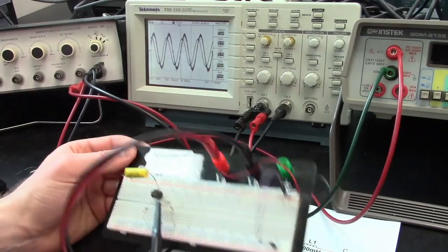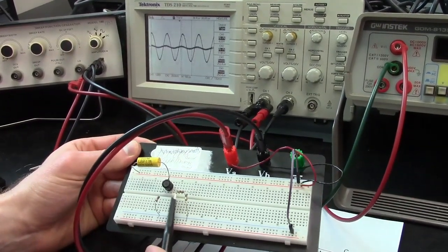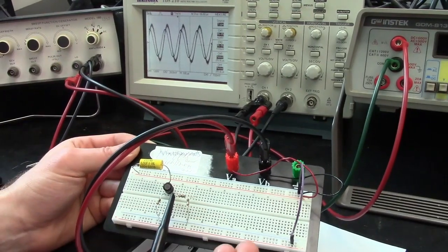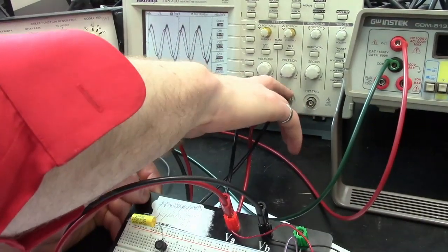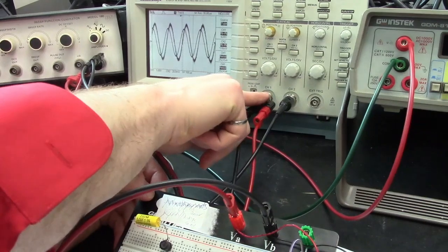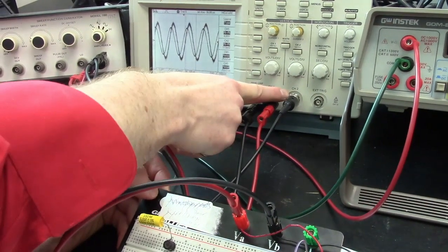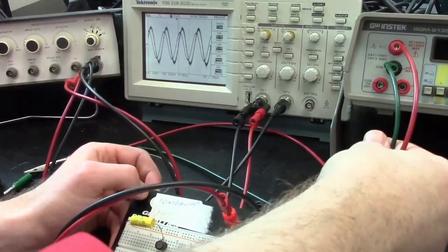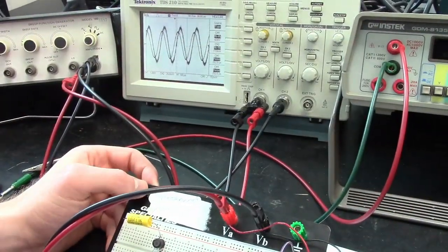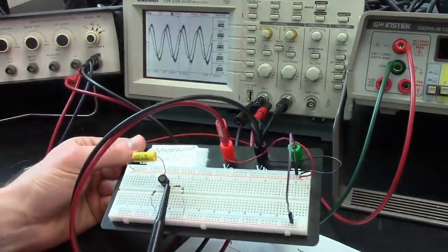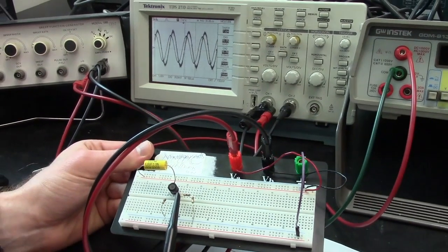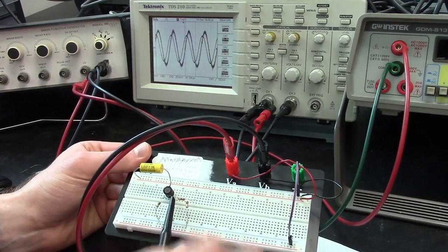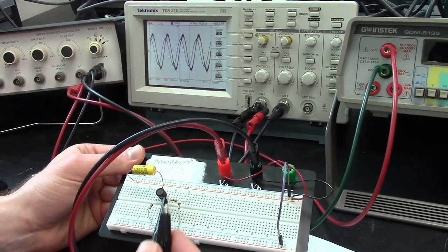So the reason we can measure anything at all when we've only connected one terminal, like what voltage is it measuring relative to, is because the scope is actually connected inside. So the ground of channel 1 is connected to the ground of channel 2. You could turn off the scope, disconnect things, and then measure that with the multimeter if you want to see the impedance between those two channels. However, to get a cleaner measurement, you usually want to use the ground right here to take advantage of the coaxial cable all the way along and cut down on the noise.